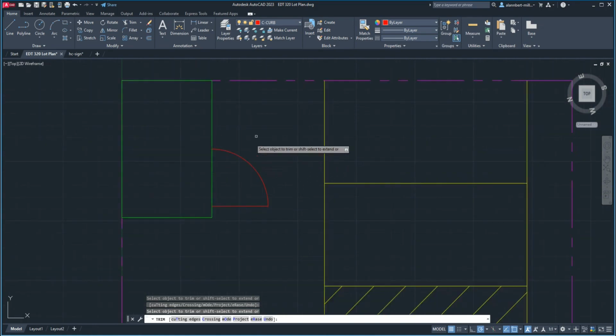And then we want another swing here, so we're not gonna do the same thing that we did before. What we're gonna do is simply select and then type in MI for mirror, and then select here and drag to the right, and it mirrors it that way. Do I want to erase all the objects? No, I don't want to. Okay, so that's the symbol for our gate.